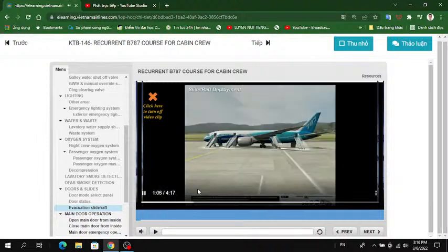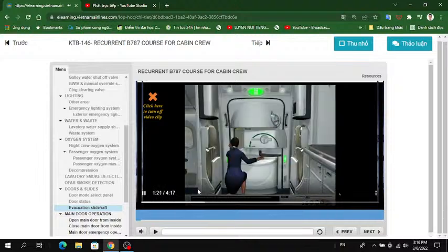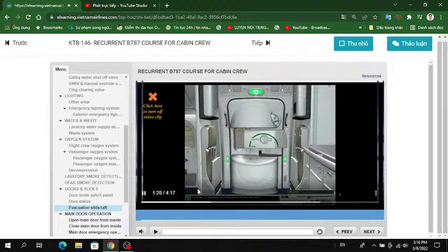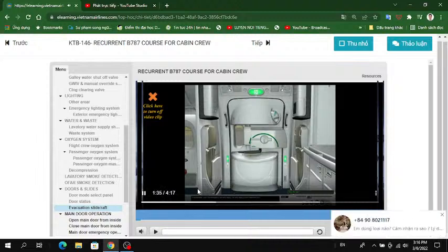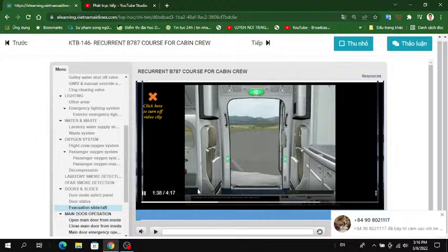In an emergency requiring an evacuation, the cabin crew is responsible for rapidly and effectively evacuating passengers through the emergency exits and down the evacuation slides. Crew members are to check for external hazards that would affect the safe evacuation of passengers. If acceptable, open the emergency exit and deploy the evacuation slide. Open the door. As the slide raft drops, an activation pin is pulled and the slide raft is rapidly inflated into a usable condition.